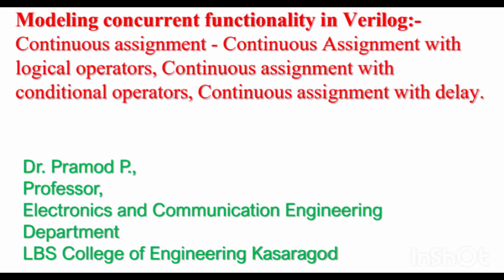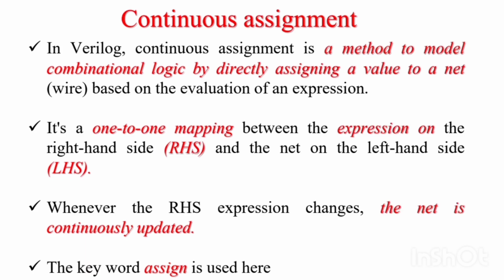Today we will discuss an important topic, that is modeling concurrent functionality in Verilog. In that we will be discussing continuous assignment with logic operators, continuous assignment with conditional operators, and finally continuous assignment with delay. In Verilog, continuous assignment is a method to model combinational logic by directly assigning a value to a net, that is a wire, based on the evaluation of an expression.